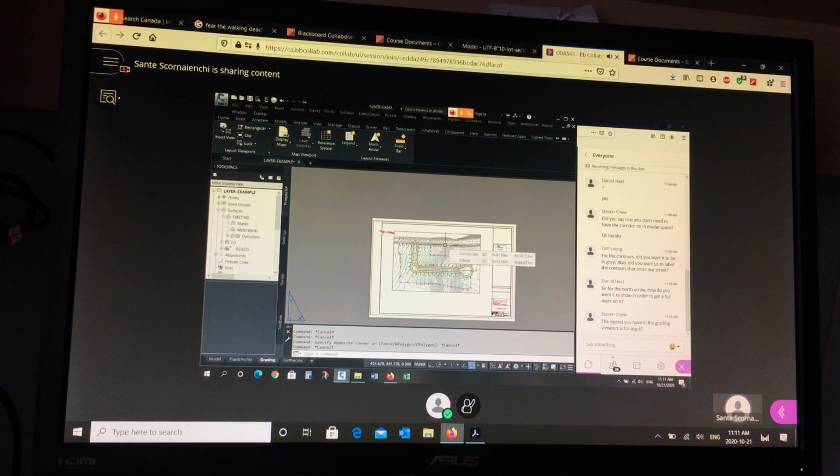We're not designing anything yet. We're just modeling the corridor so we can get those front lot corners. We modeled the existing ground so we can get the back corner elevations. And then once you have a front and back condition, you can design what has to happen in between. And that's today's discussion. We're going to do some of that together.